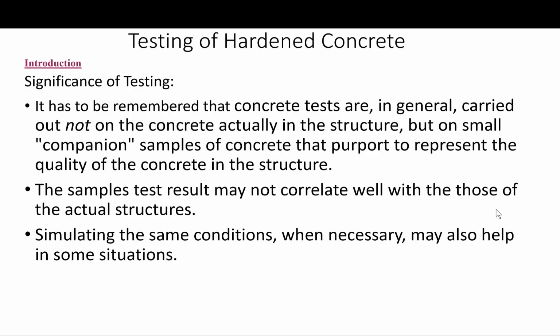An example of how the discrepancy between real and measured concrete property arises: let us examine the compressive strength. The concrete in a standard cylinder is subjected to different compaction effort from the concrete in the structure. Also, the size differs from the size of the structural member by several orders of magnitude. The temperature and relative humidity of curing are different. Also, the cylinder remains free of stress until tested, while the structural members will be carrying at least some load. They'll be under load.